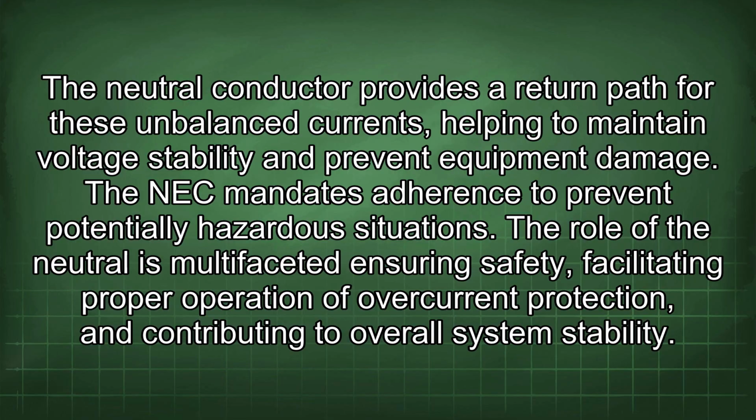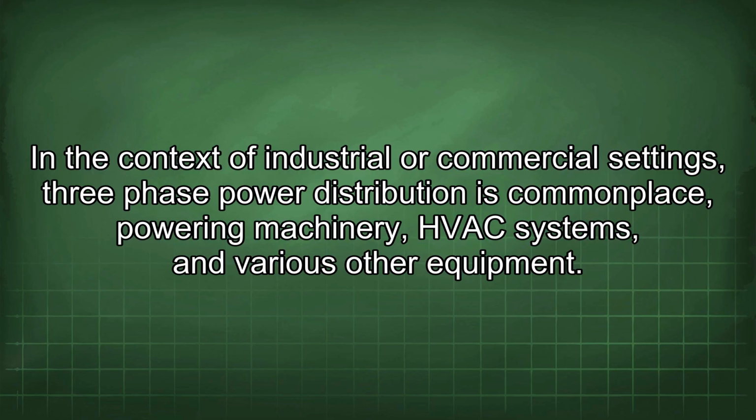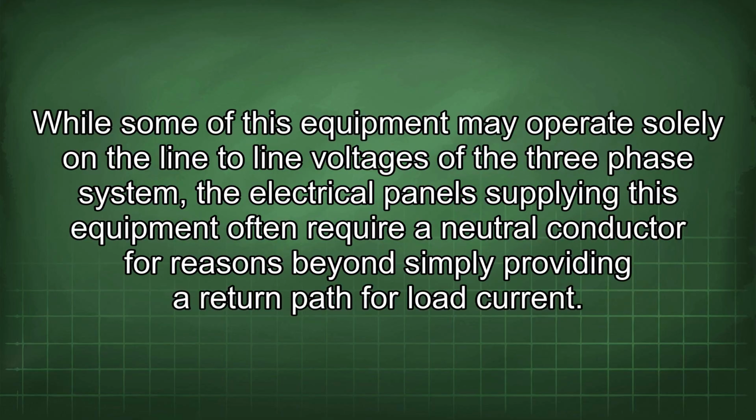The NEC mandates adherence to prevent potentially hazardous situations. The role of the neutral is multifaceted, ensuring safety, facilitating proper operation of overcurrent protection, and contributing to overall system stability. In the context of industrial or commercial settings, three-phase power distribution is commonplace, powering machinery, HVAC systems, and various other equipment. While some of this equipment may operate solely on the line-to-line voltages of the three-phase system, the electrical panels supplying this equipment often require a neutral conductor for reasons beyond simply providing a return path for load current.